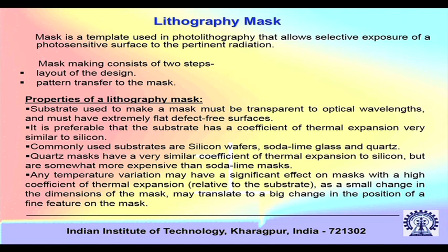What are the properties of the mask? The mask must be transparent to optical wavelengths and must have extremely flat, defect-free surfaces. It is preferable that it has a coefficient of thermal expansion very similar to silicon. It is just like, think of the mold and the pattern in casting. The pattern is like the mask.